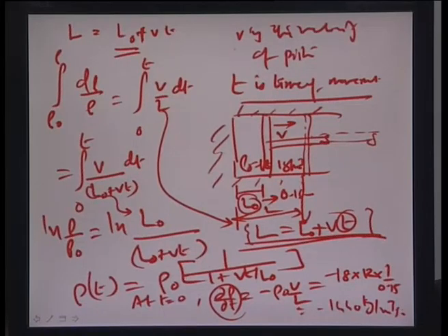As you found out here, the continuity equation can be very easily used for this kind of compressible flow problem as well, where density varies with time, as well as the earlier problem which was that of incompressible flows. In microscale, if you consider the flow mechanics, mostly flows are treated to be incompressible and strictly laminar, because although there are two-phase flow problems at the microscale, the modeling becomes extremely complicated and difficult, so we will be limiting ourselves mostly to single phase flow problems in such a situation. This brings us to an end of this particular lecture.